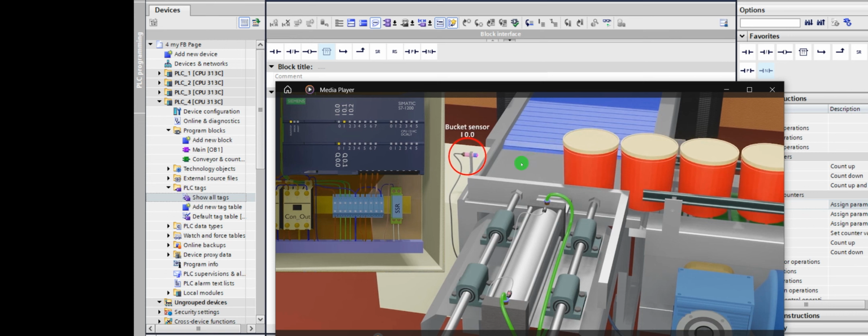You remember that I also made mention of how to use sensor with a relay, that you will learn how to use sensor with a relay system. So if you watch how this one works, once this one gets activated, this one will get activated as well. Okay, this sensor has in this relay. This sensor is responsible for activating this relay. And this relay now is responsible for shutting down this and activating this, because this sensor only has three cables.